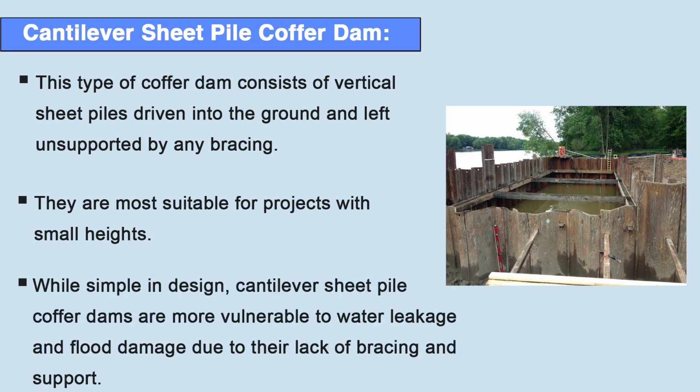While simple in design, cantilever sheet pile coffer dams are more vulnerable to water leakage and flood damage due to their lack of bracing and support. They are effective in situations where the water level is not high and the water pressure is manageable.